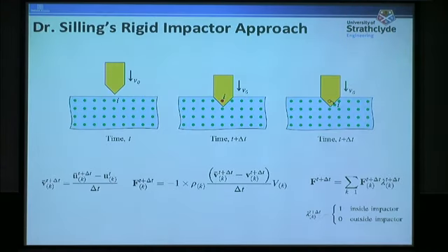And as you will see, Peridynamics is also very suitable for impact problems, and there are different ways that we can simulate impact. It's a very simple algorithm that Dr. Silling proposed a long time ago. Basically, we are always checking to see if there is any material point inside an impactor. If this is the case, we just say that this should not be the case, so we move the point outside of the impactor, and this is how we can model a contact situation.